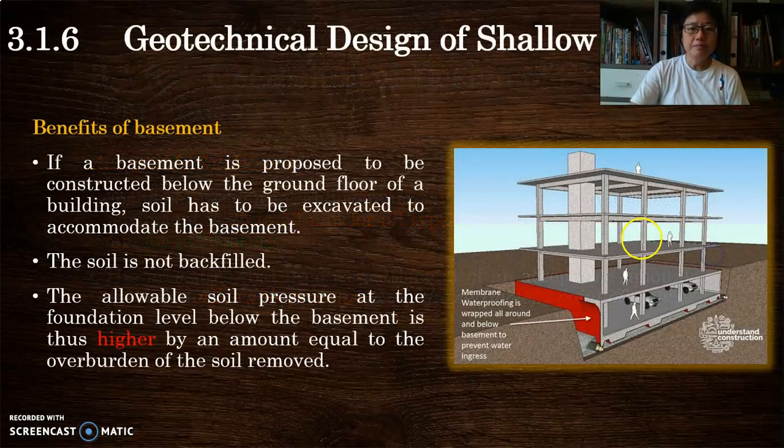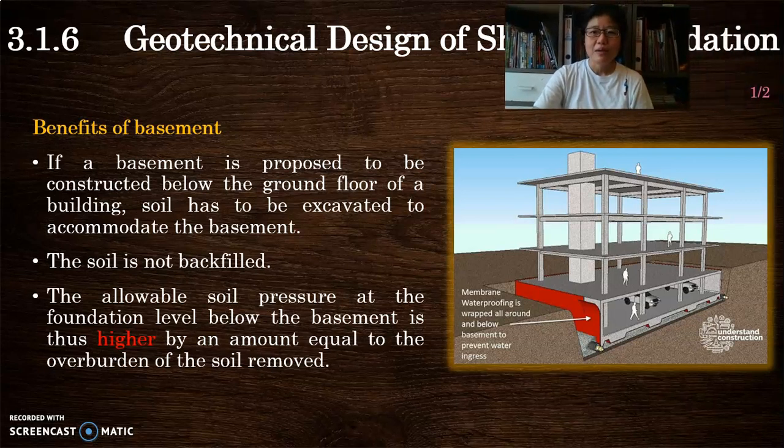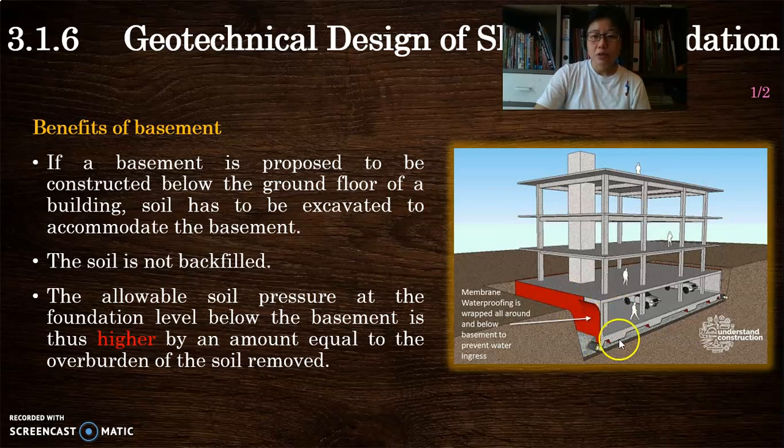Okay. Now, we are going to have a small discussion about why basements are nice to have. As you can see here, it's a high-rise building, and this is your pad footing. You can see some parts are thicker, and they are thicker near your columns coming down. It makes sense, right? Where the loads are coming down from the columns, you want it to take more load than the parts that do not have a column coming down. Hence, the parts that are near or under the columns are usually thickened. That is common for a raft foundation design.